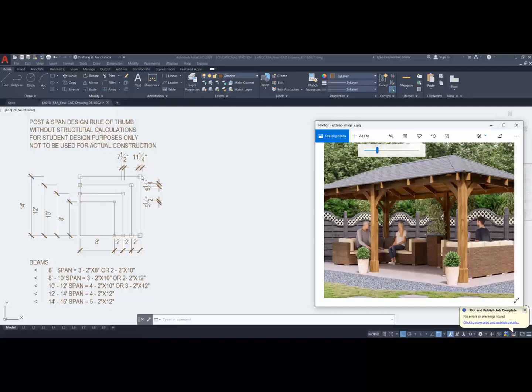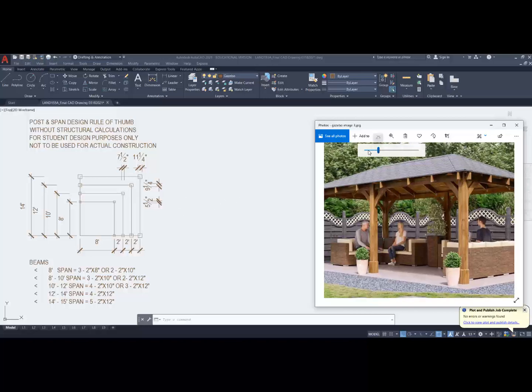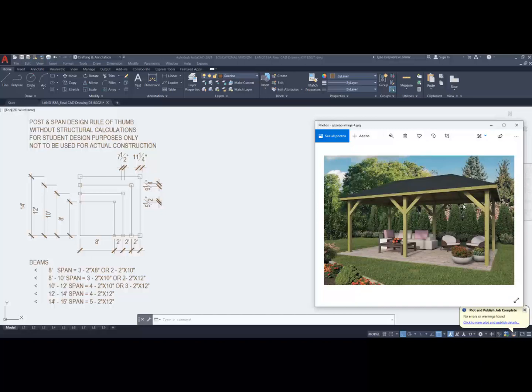You'll notice here what I've drawn is the post and the beam, but the actual roof will extend over that edge. It extends anywhere from 12 inches to 24 inches from the center of the beam out to give that overhang, that extra coverage. So you can get extra coverage by bringing the posts in, but allowing the roof to slide over top of that. This is another example that reveals how the ceiling joists sit on top of the beam.